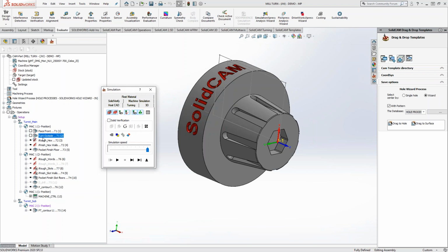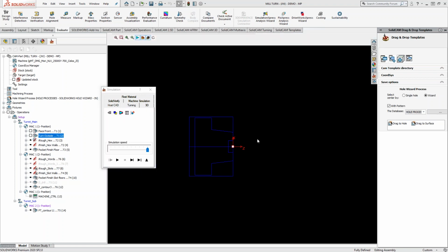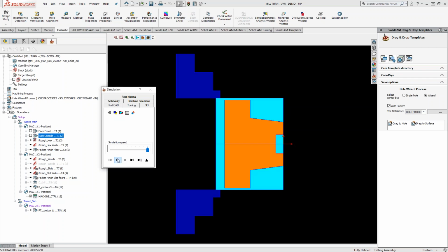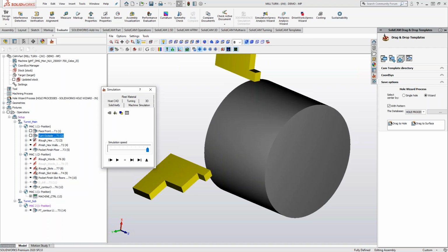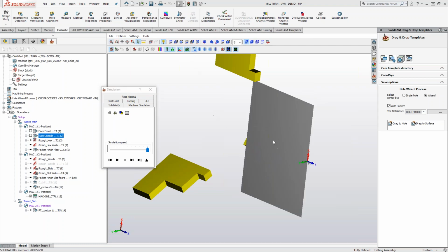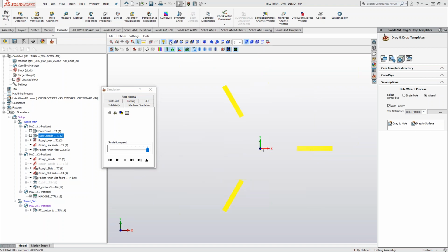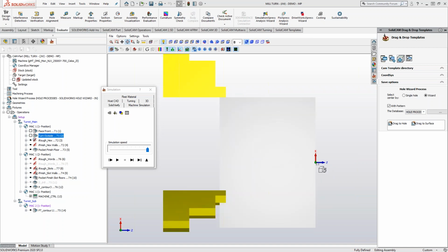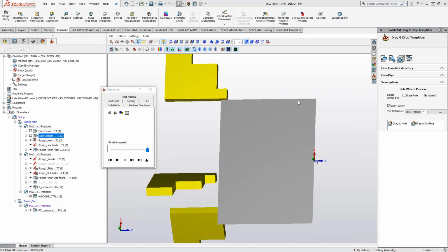In the simulation, especially for these turning toolpaths, there is the turning simulation. It just shows us the profile. We can see the tool going through and doing its thing. Now, in Solidverify, we can actually get something very similar. You can see there are some extra icons here, and this 2D one gives us that similarity. That just gives us that profile. Let me get a better view. Now, that's not necessarily the turning view. That's the turning view right there. Let me angle that so we get some shading. So that is actually the cross section down the middle. So we can see the turning toolpaths, but using Solidverify functionality, right?